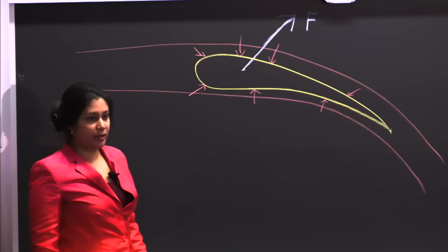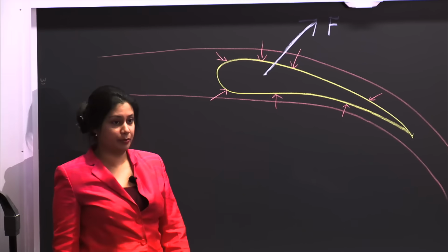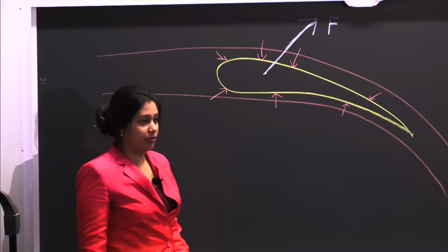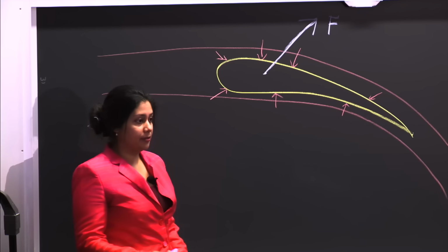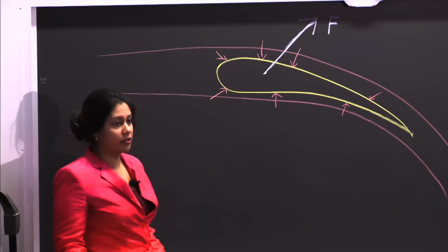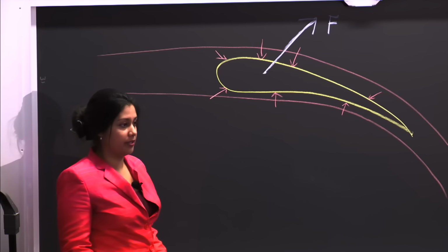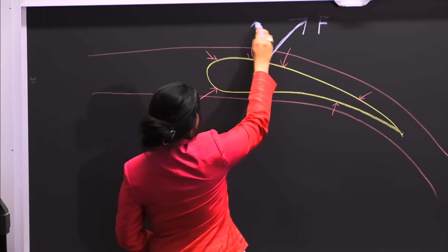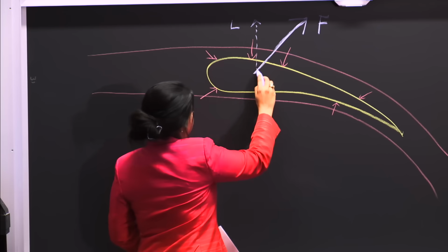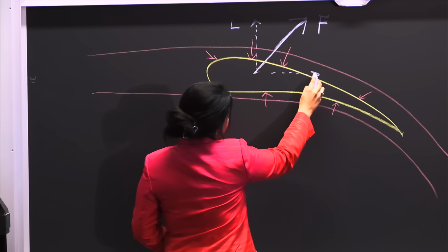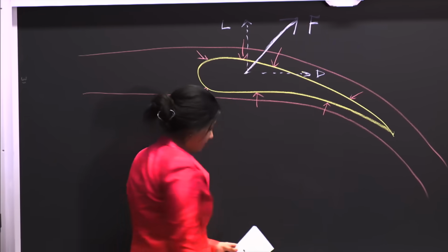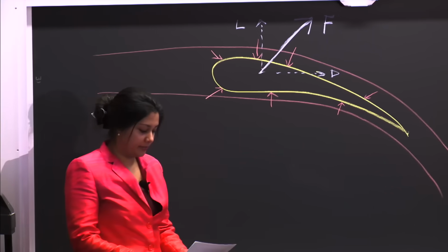So that's the force it generates generally when the fluid is moving forward. Force is a vector, so it has direction as well as magnitude. So there's a vertical component and a horizontal component to that. We call the vertical component the lift. Does anyone know what we call the horizontal component? Drag. Good job. All right.